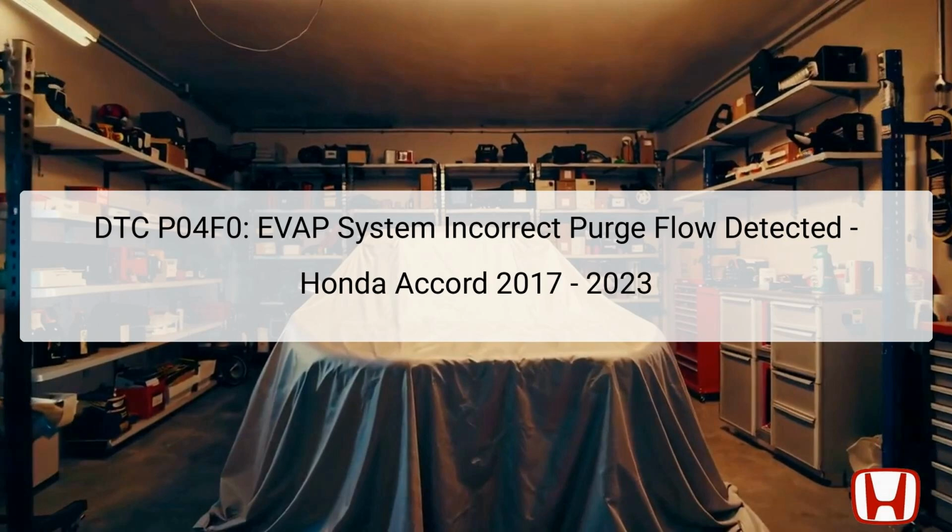The EVAP system typically includes several components, such as the EVAP canister, the purge valve, and associated tubing. The canister is usually located near the fuel tank, while the purge valve is often positioned along the engine's intake path. When this code is triggered, it can indicate issues ranging from blockages, disconnections in the hoses, or failure of the purge valve itself. Proper diagnosis and resolution are essential to ensure emissions compliance and optimal engine performance.